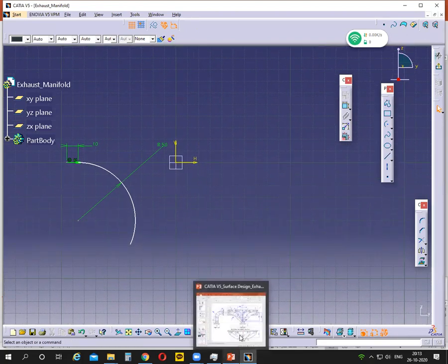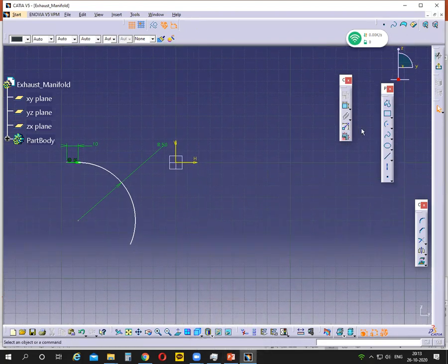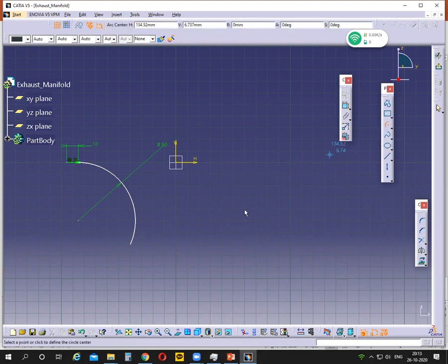And here, again one more arc, another side. Okay, center point is somewhere here. So another arc touching the first arc. Okay. So center point. So avoid the automatic constraints. Okay, here do not start from here. This is okay, and do not start from here.